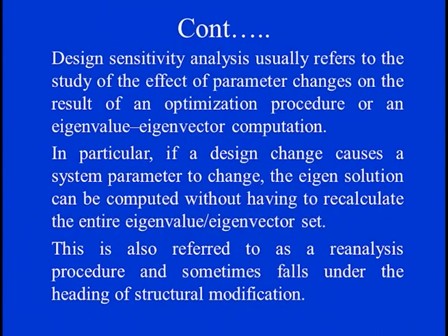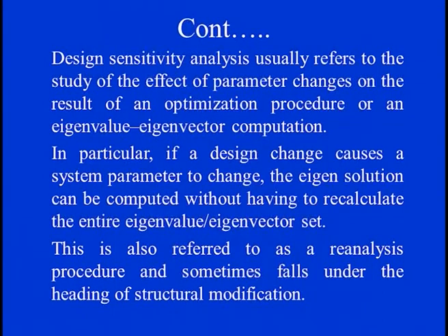In particular, if a design change causes the system parameters to change, the eigen solution can be computed without having to recalculate the entire eigenvalue eigenvector set. And if this is possible, whatever changes are there are compatible and can be immediately adopted. This is also referred to as a reanalysis procedure, and sometimes it falls under the heading of structural modification.